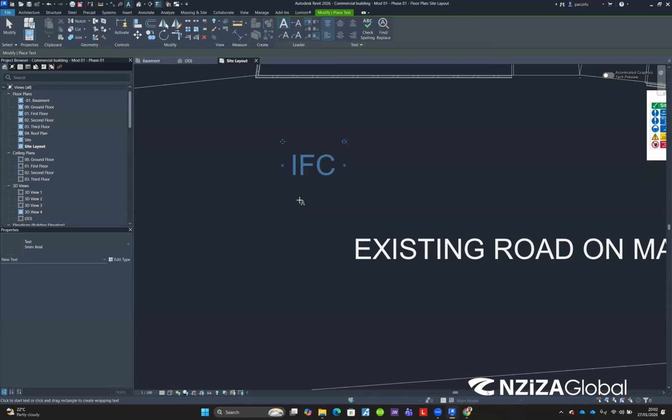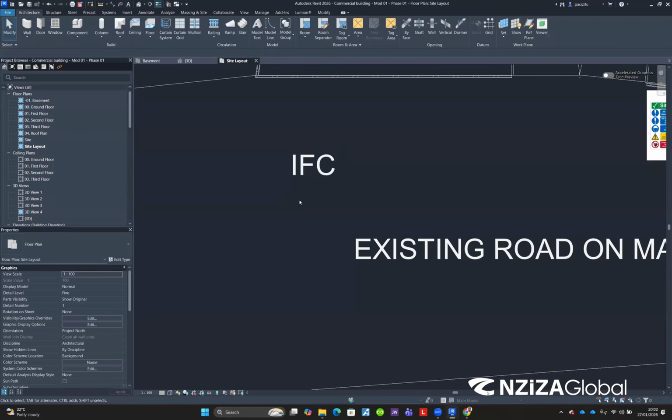Somehow Revit has an easier way to redraw or to use those files. But for now, ArchiCAD is very poor in IFC files. ArchiCAD can't export a good IFC file like Revit. For example, if I take a file from Revit and export it as an IFC, it will go with all the details like walls, ceilings, floors, slabs. All the things will be exported as they were in Revit.